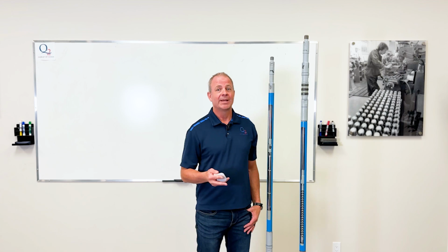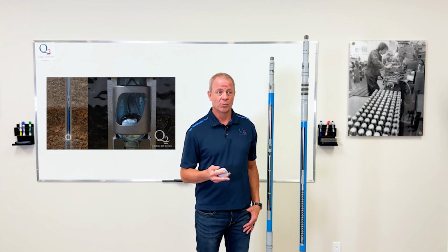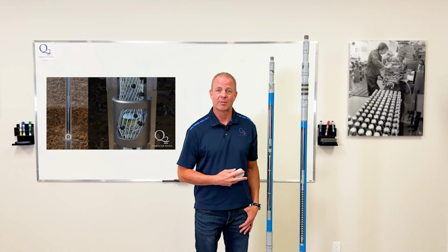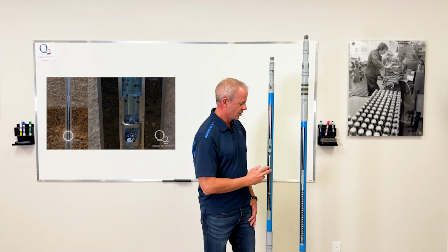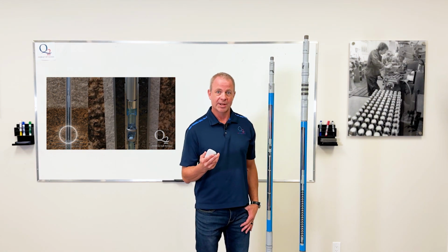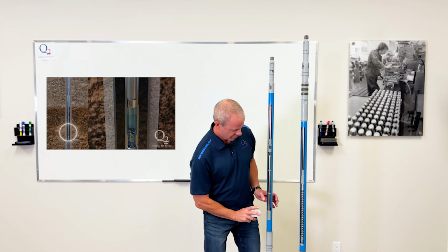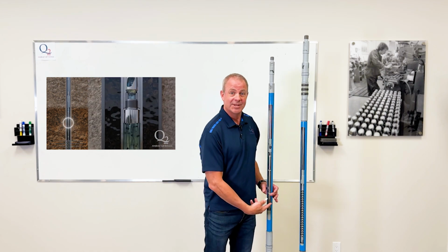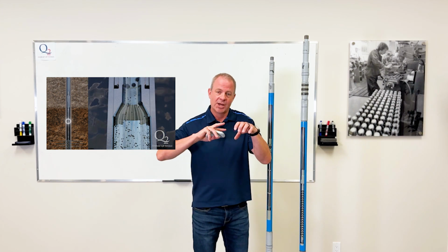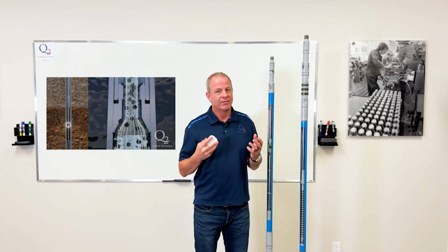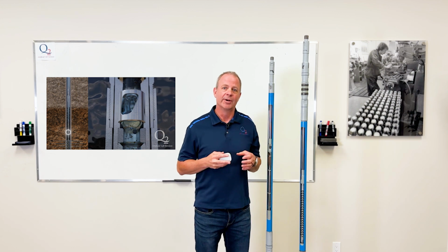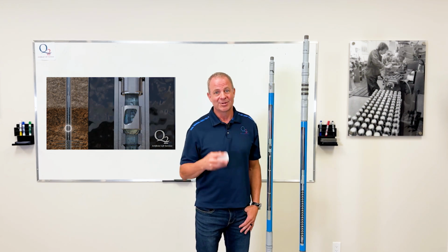Now, if you remember at the beginning of the presentation, I asked you a question. It was, why are the vortexes clockwise and not the other direction, counterclockwise? Well, originally we did some counterclockwise turns in here, but some of the structural factors hurt us. What happens on these pumps is you always turn the pipe in this way when you connect the pieces. So when you turn the thread together, any kind of piece that has a clockwise vortex, you're going with the thread. So it's not only fluid flow that we have to really worry about, it's also the structural and the strain and the pressure we put on our vortex valves. So there's your answer, and I know I promised that to you.